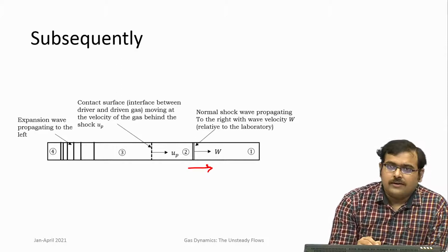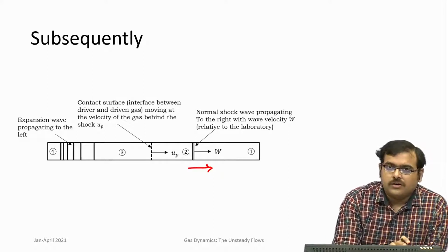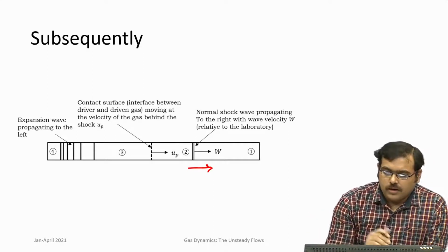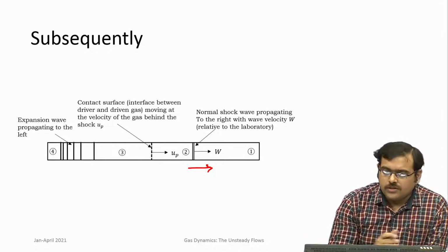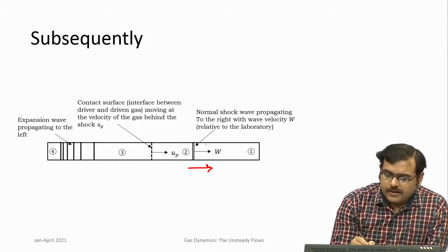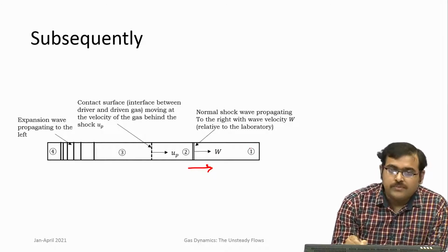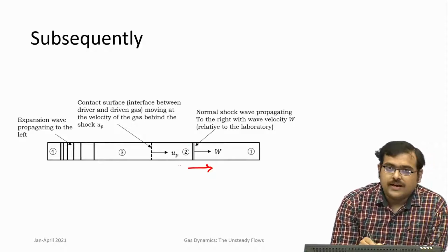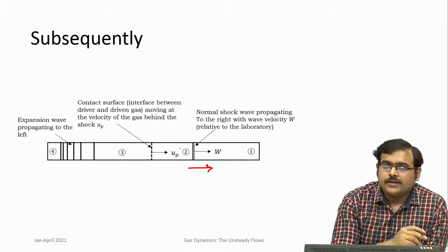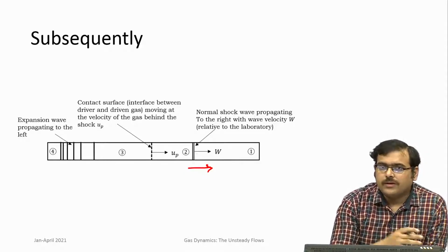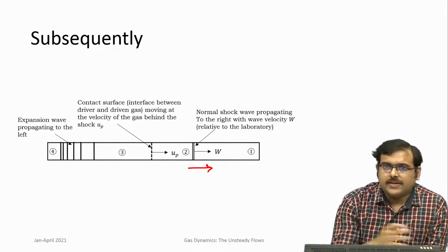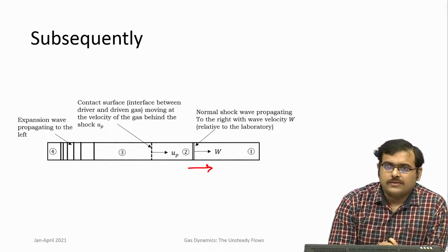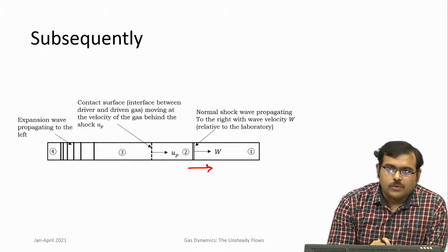They are regions within the shock tube as the shock wave progresses into the driven section. So, driven section is 1. Just behind the shock wave, the region of gas is region 2, and we know that it is a moving shock. So, when the shock wave moves, it carries gas with it. So, that phenomenon is quite unlike sound waves.